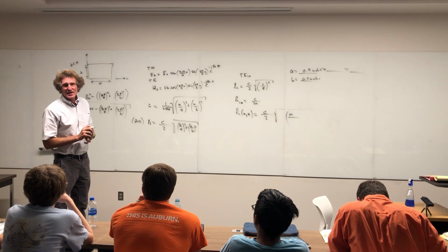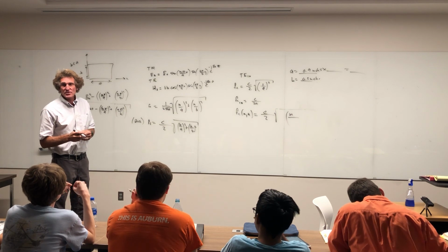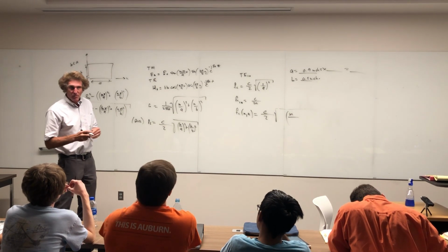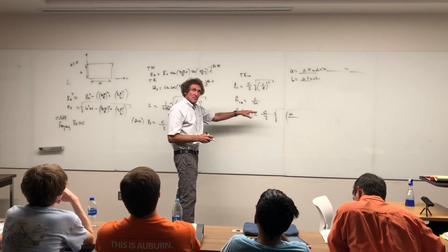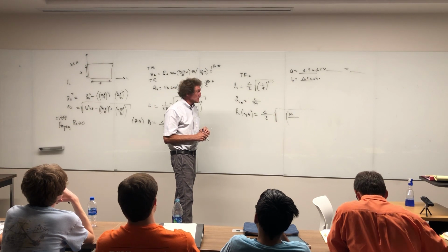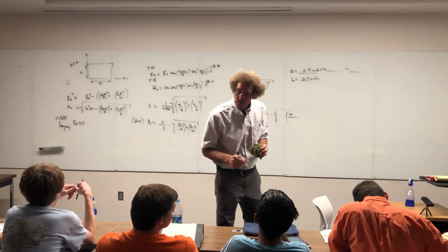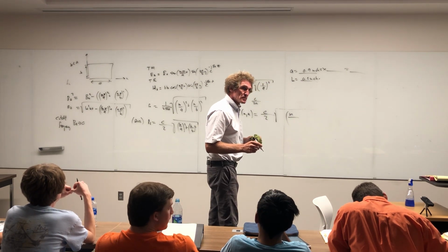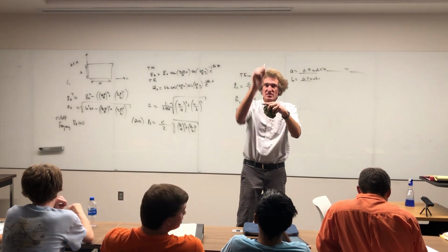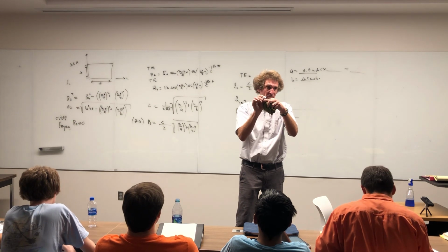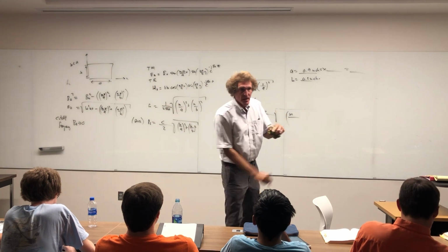There are some other oddities, but really for the most part, at least on your first crack at this stuff in the real world, you're just going to be propagating energy in one mode. Almost guaranteed. And you're going to go probably 30%, 40% above the cutoff frequency. Yep. Are the frequencies for cutoffs inclusive? Is the cutoff frequency the frequency where it starts propagating? Yep, anything above there. You normally don't go right at the cutoff, because at the cutoff, energy is bouncing back and forth on the guide, like a parallel plate capacitor, just ricocheting. Then you go a little bit above it, then it's banging like this, going down. And I'll get to that.